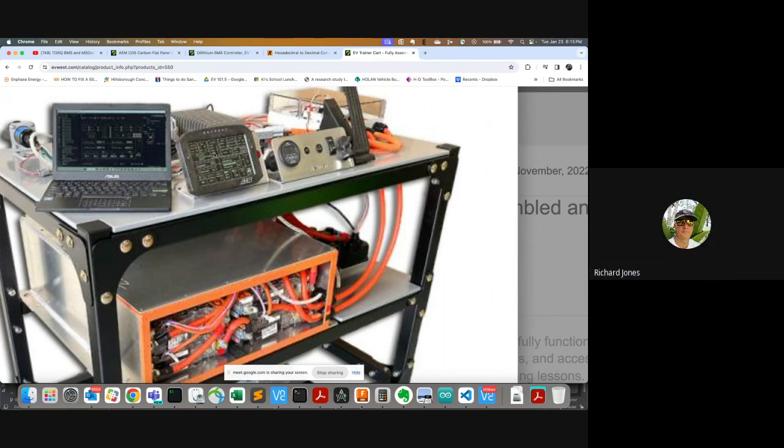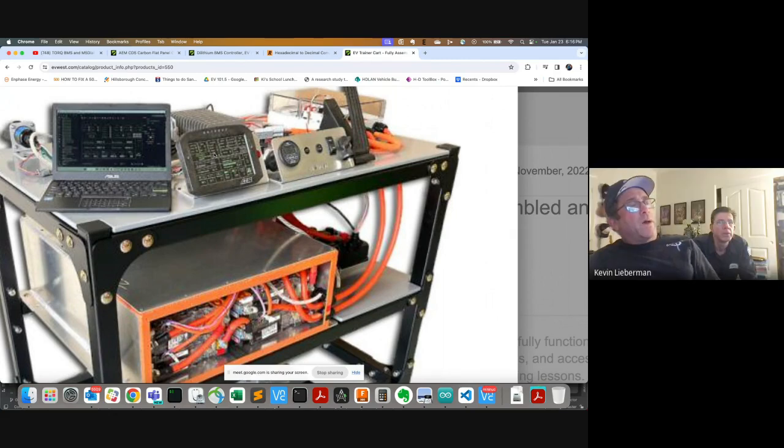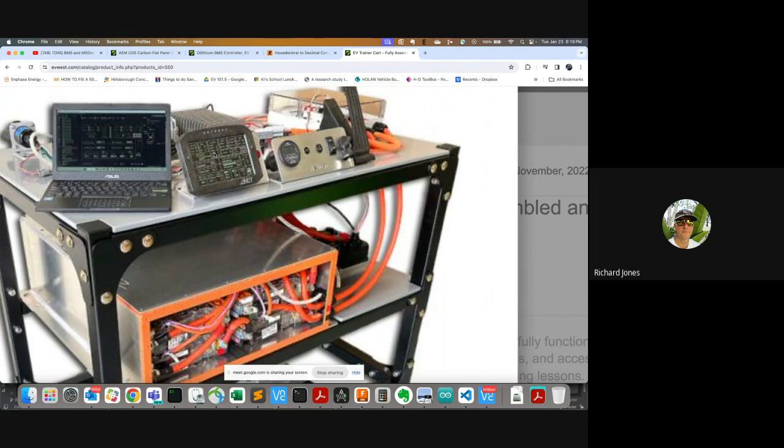So the AEM can have a screen that shows the cell voltages and the temperatures. That's basically a bit of software running in that fancy expensive display that decodes the values off the CAN bus. So this cart's awesome because you've got a CAN bus on there with a motor controller, BMS, I'm not sure what the DC or current sensor is, and then you have a nice display there, which is interpreting those CAN messages for you.